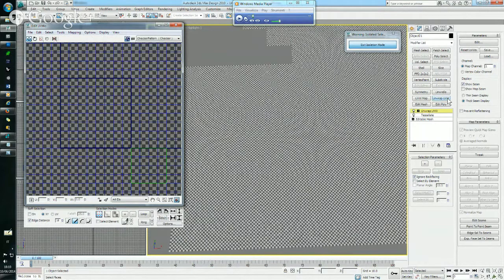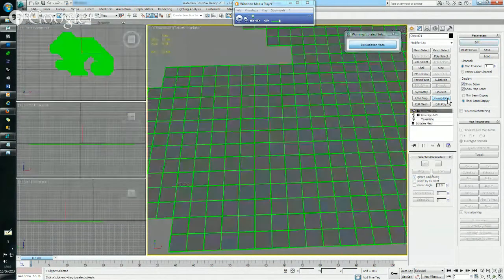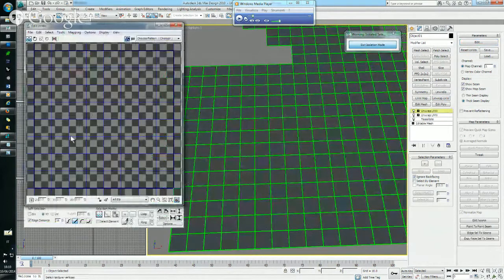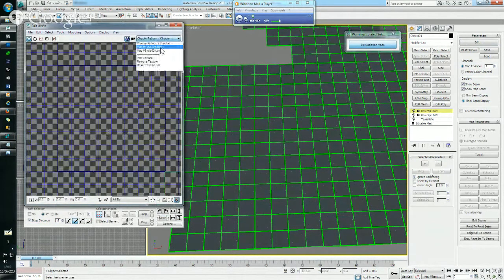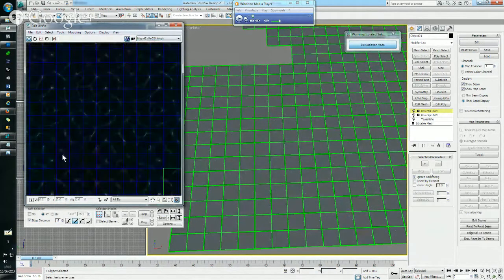So each time I press the unwrap edit, I have the central viewing of the UV coordinates. I have the snap already enabled, and I have the grid with 1/2 of click. So this is 1 click high and 4 clicks wide. This is half of a sector high and 1 sector wide.